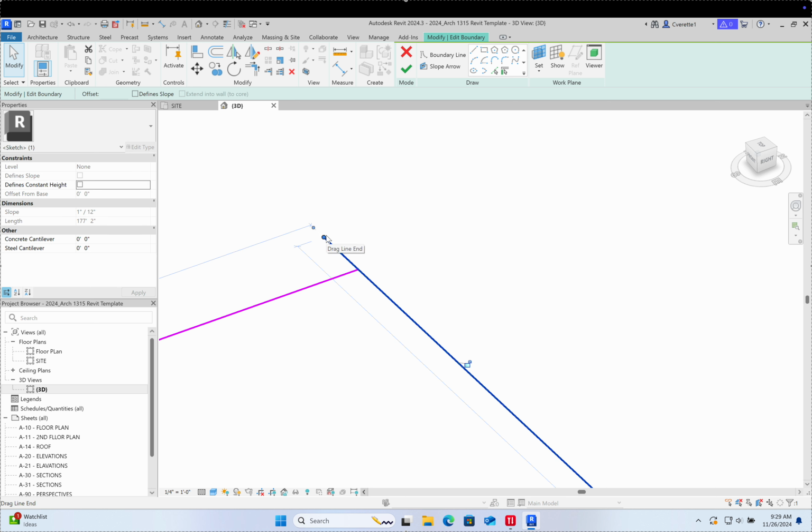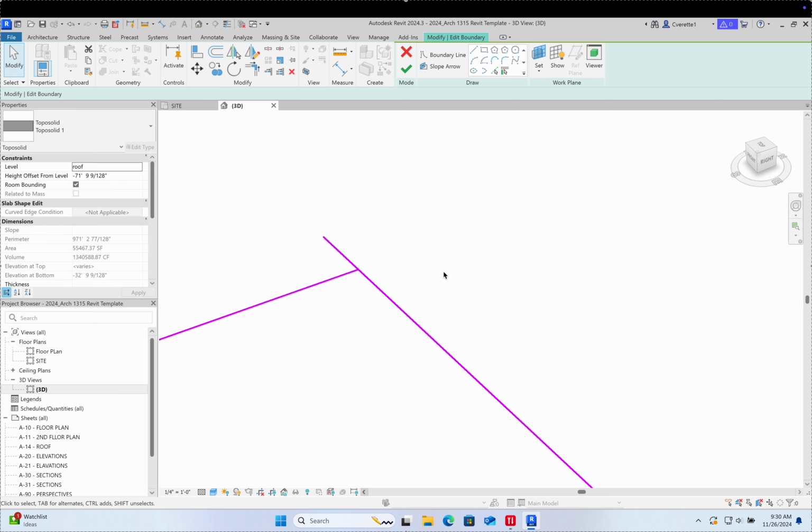It's literally just TR. The way that commands work in Revit is basically a 2-key system. So very often you'll hit 2 letters. It's very weird, trust me. But you kind of get used to it. So in my case, TR will keep the lines that I click on. So if I click on this side and this side, oh, it's gonna keep that one and actually trim that one off. In my case, that's not what I actually want.